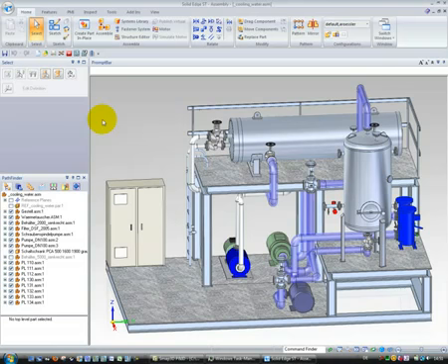The first important point which must be available before we start the 3D pipeline creation is the library with all required components. That means equipment, valves, fittings, all the parts and assemblies that you would like to use automatically during the pipeline creation with the piping software from us. If parts of the library or the whole library is not available or valid for your requirements, then Smap 3D piping can't create your required pipelines automatically.